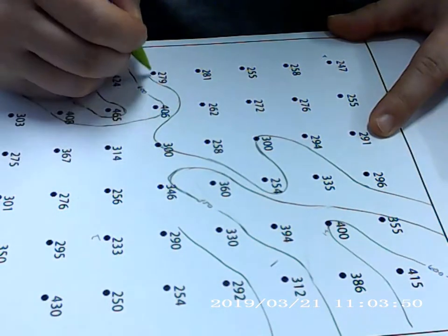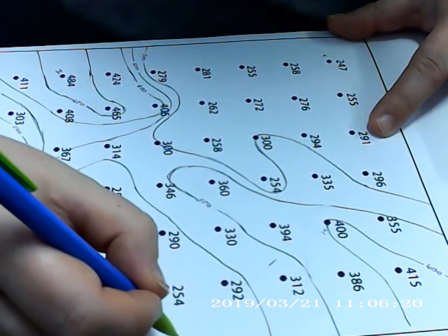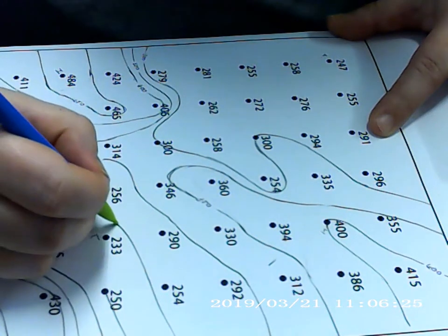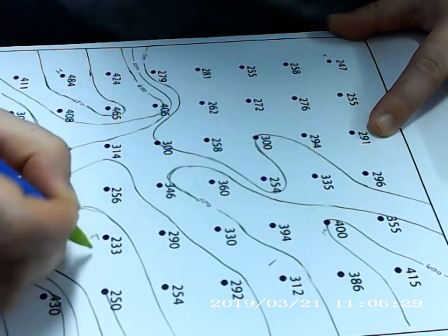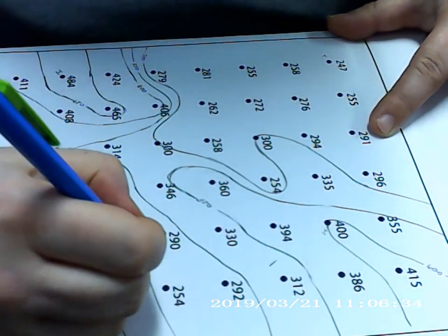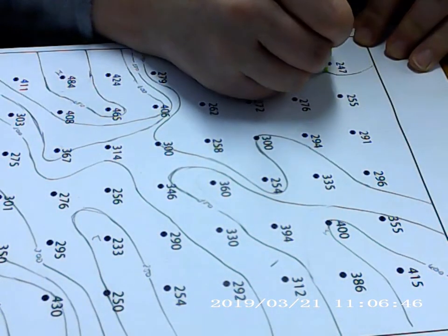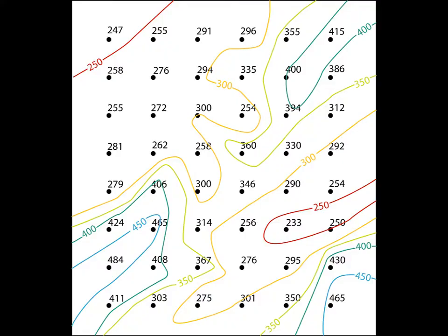We continue contouring until we have separated all the areas of higher and lower values with the appropriate contour lines, making sure that any reversals of slopes are indicated by repeating contours. Now the final contour in the top right goes in. The result indeed resembles hills and valleys as expected.